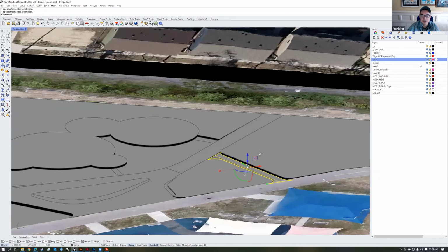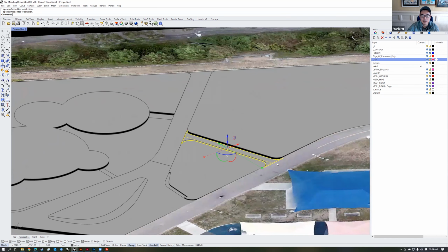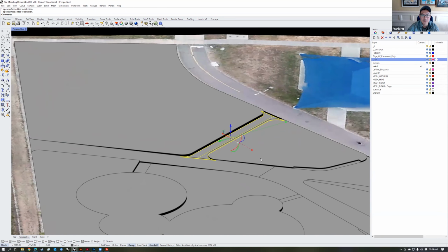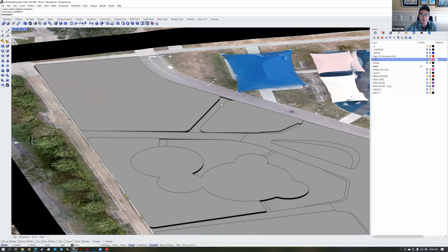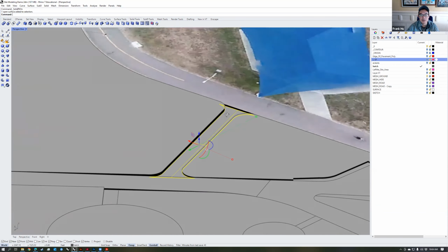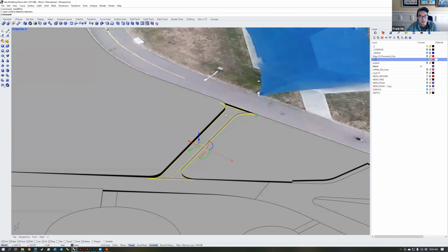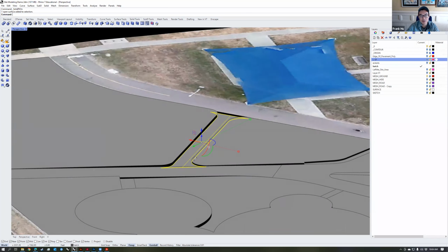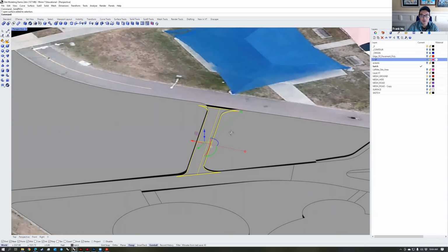Another technique you can use, and let's use it on this path right here, is the solid control points option. In the solid tab up here, the solid tools, there's a button called turn on solid control points. Clicking that usually brings up the control points of the surface that you can manipulate. But the geometry that you generate via this method of hatch explode surface that I showed here doesn't actually have proper solid control points. So you need to rebuild these surfaces in order for this to work.